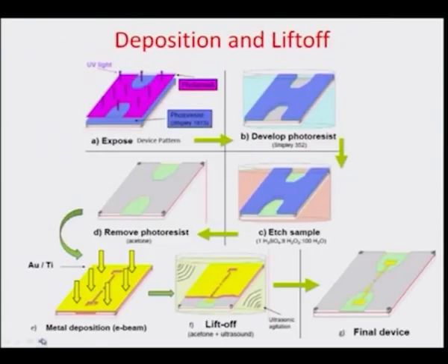One more example is what you do with deposition and lift off. Here for example, you are actually exposing the resist to get a shape or feature through which you are doing some etching action. So, you are actually removing this gray layer here up till the green layer, which is probably the etch selective layer. So, the etching stops here, and then on this you have another masking strategy, and using this masking strategy you are now trying to deposit gold and titanium, and then trying to remove the resists in these portions.